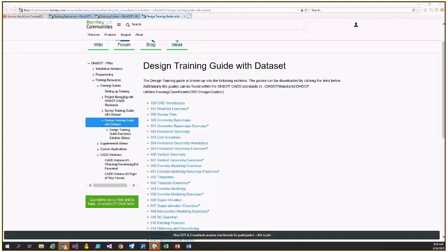And when that happens, the SS10 update, just a quick note, which we'll send out more on: for SS10, the installation path changes. That means your shortcuts for launching like O.CAD and SS4 won't work anymore. So you have to recreate shortcuts. I already have them created and they're in the CAD tray, which I'll show you how to get to in upcoming information, or you can run the client configuration tool.